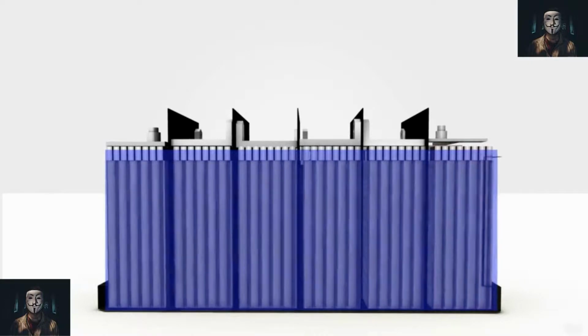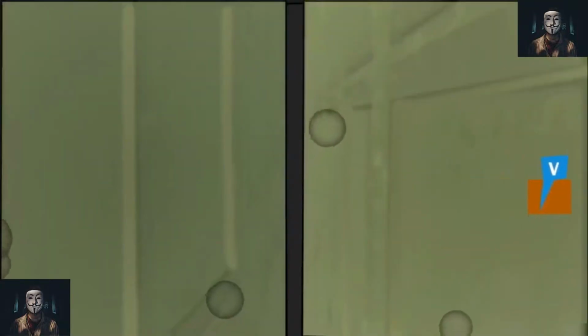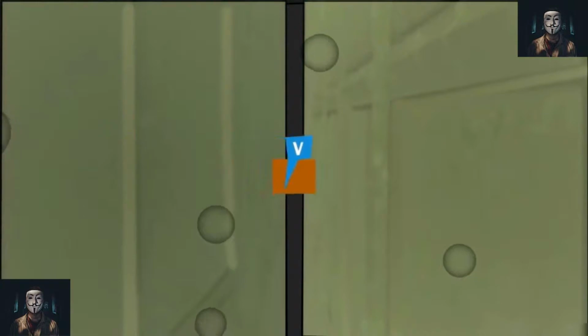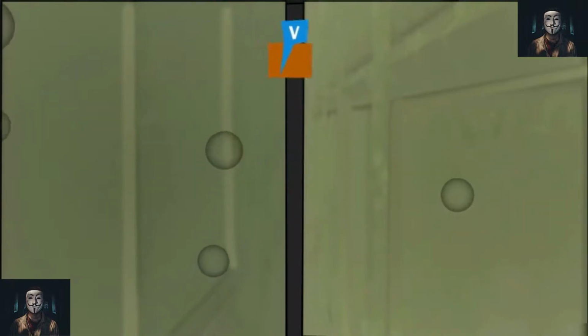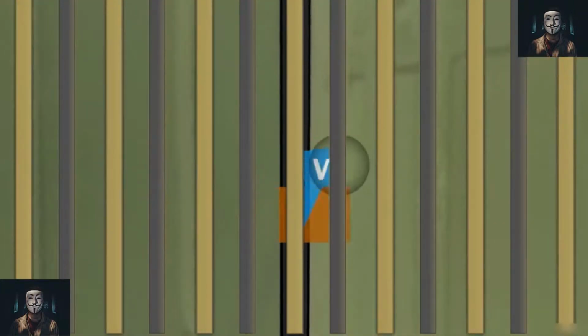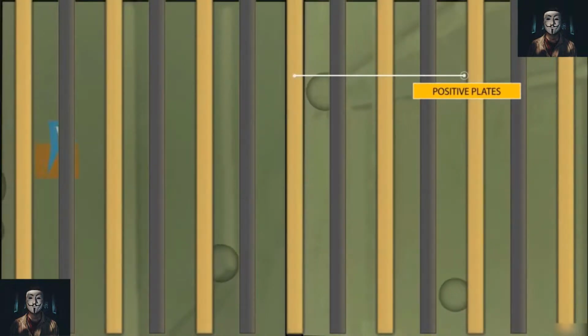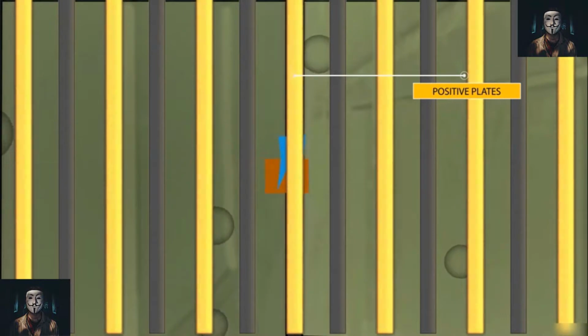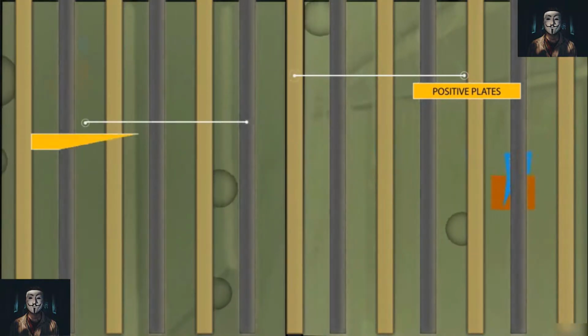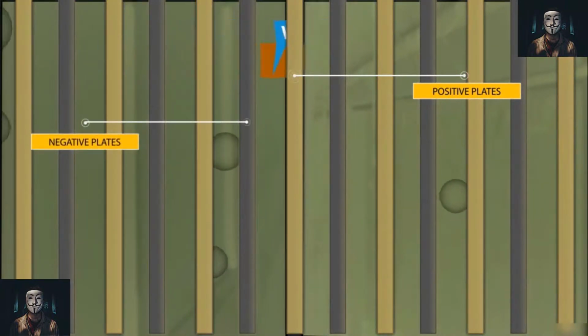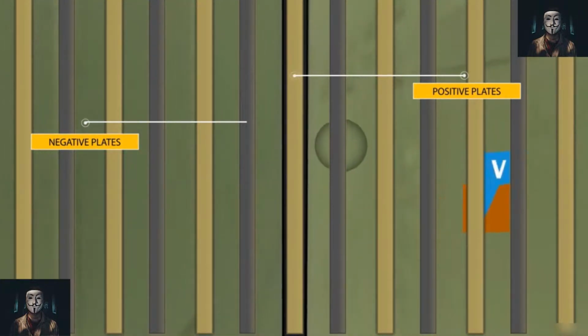Measurement of battery condition by heavy-duty discharge should only be carried out on a fully charged battery. Heavy-duty discharge is carried out with a specialist item of equipment. This consists of connecting a low-value resistor in circuit with the battery for a few seconds and measuring the voltage drop. This test applies a load similar to that of the starter circuit. In general, the voltage should not fall below 10 volts.